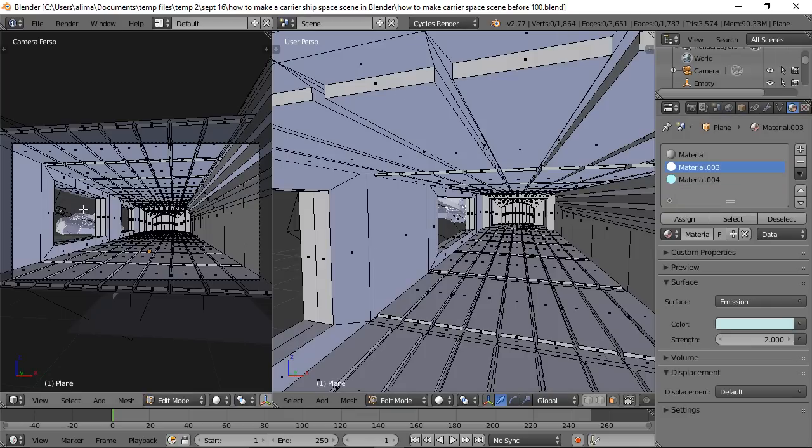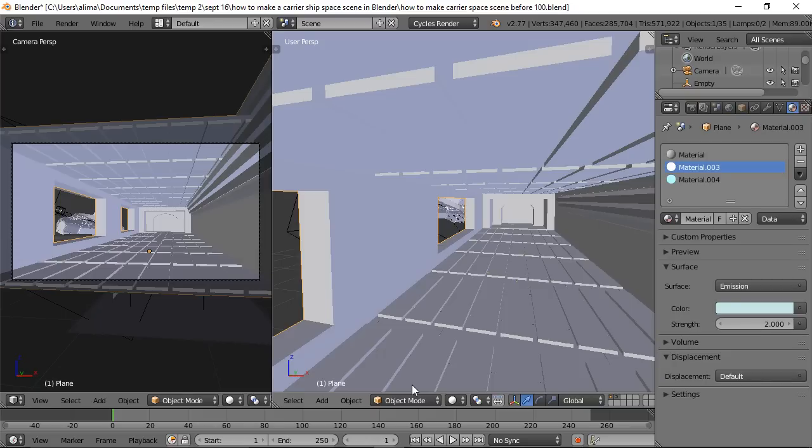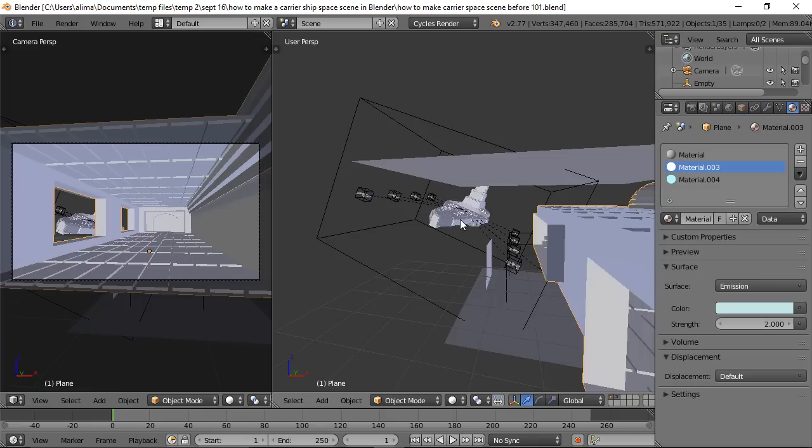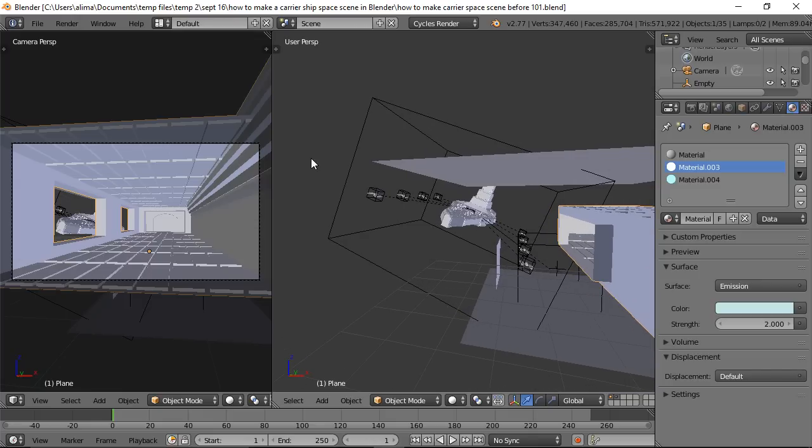When we look here, it would be nice to have some space out here. When I say space, I mean outer space. So what we're going to do is click here and then go to object mode. I'm now going to hold Shift and the middle mouse button to pan, like that. I'm then going to right click to put the 3D cursor right there. We put the 3D cursor right there because in Blender, where the 3D cursor is at is where objects tend to come into Blender.